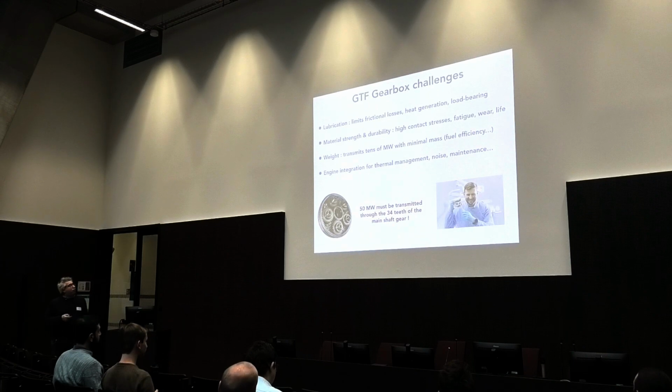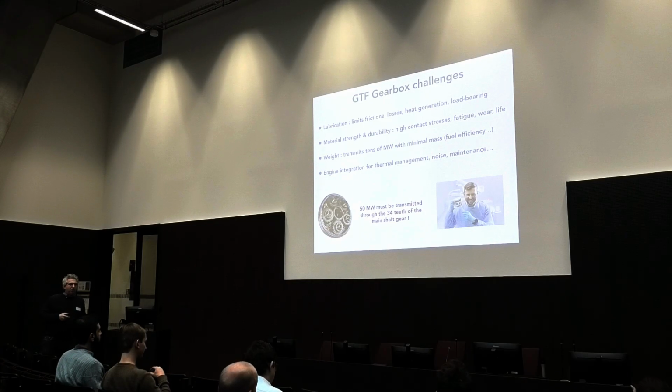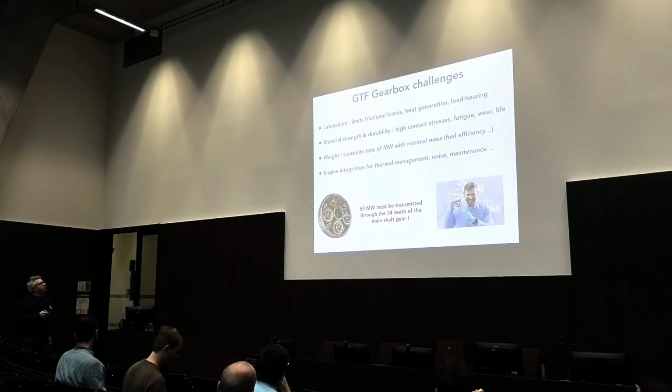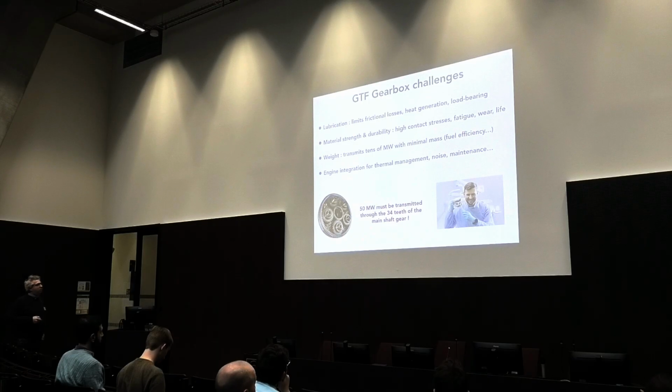And it also poses some challenges in terms of lubrication, to limit the frictional losses, the heat generation, the load bearing, but also in terms of material strength and durability, in terms of weight, since we are working with an aircraft engine, so the weight is the first enemy, and in terms of engine integration for thermal management, noise, and maintenance.